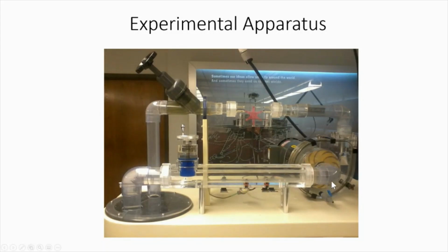So this yellow thing is your turbine blades, your pump blades, and this is where it's going to take the fluid in and push it out. This is your outlet. This is your inlet. This is a turbine flow meter. When the fluid goes through here, it's going to rotate, and according to its rotation, you read however much flow rate is going through it.